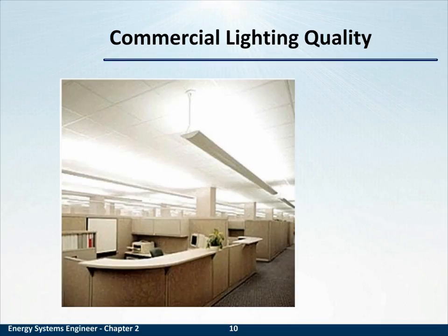In this example, as we discussed just briefly in lighting design, I wanted to give an example of a lighting designer anticipating and solving a problem before it starts. And that is the problem of glare and shadows in an office environment. Shadows are mitigated largely by having a lot of fixtures so that the light comes at your desk in many angles.